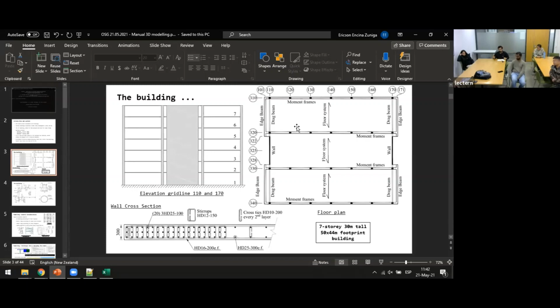The only thing they do is grab a shell element, and the procedure asks the domain, asks the element, what are your nodes? Once it has the nodes, the procedure asks the domain what the coordinates of these nodes are. And then it calculates the area and the tributary area of that shell to that node.